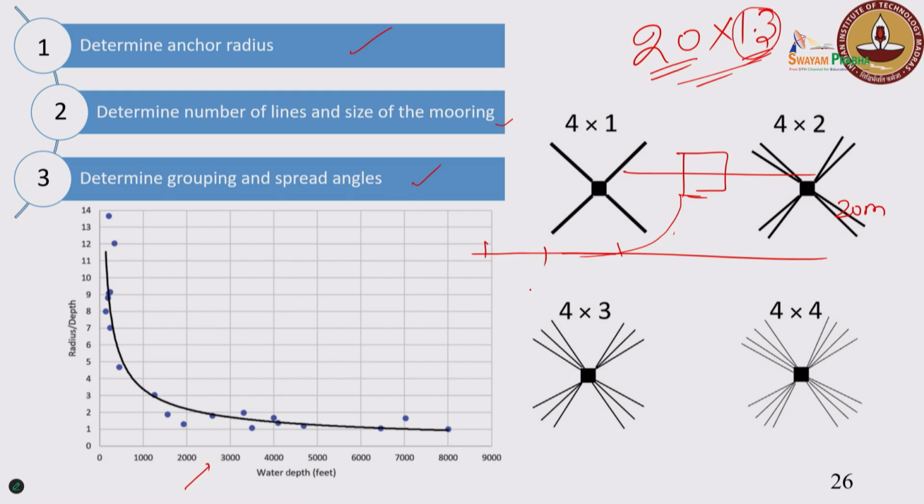If my length on the seabed is very less, and this floater is going to move in this direction, quickly the line will come into tension, right, and that load will act on your anchor, which you are not interested in. You don't want to transfer more load to the anchor. Anchors are there to help you restrain it, but you should not continuously transfer the load.